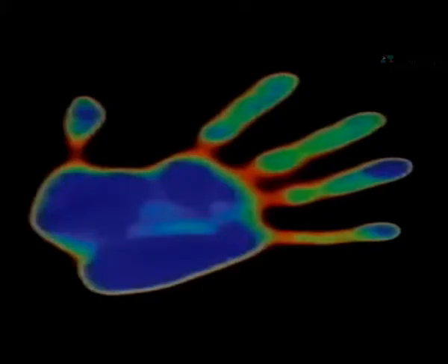This is a technique where we get a dye which you can paint on a surface, and the dye changes its color depending on the temperature. The picture I am showing you here is a very thin film of plastic on which this dye has been put, and at room temperature its color is black. So when you put your hand on it, the hand is warmer than the room temperature, and you can see this entirely. You get a complete thermal map of the skin temperature in this particular case. So this is a very nice technique by which a complete map of the surface temperature can be obtained.